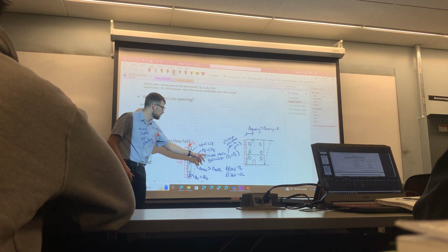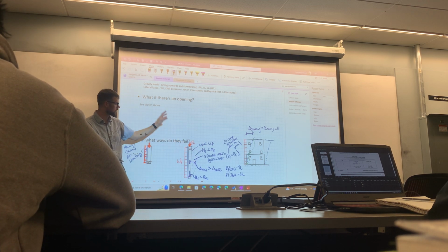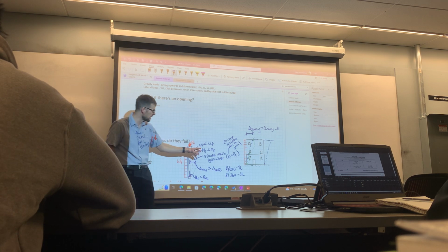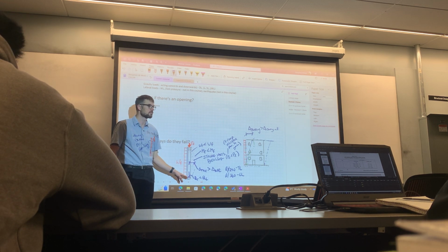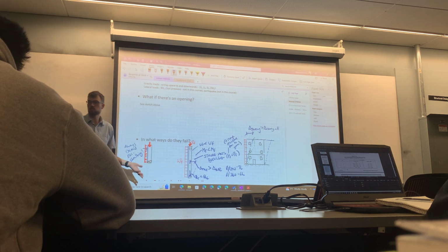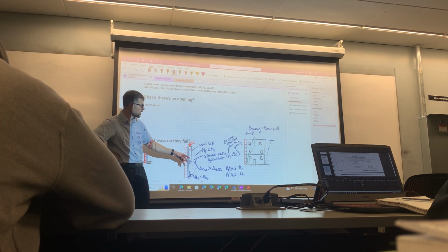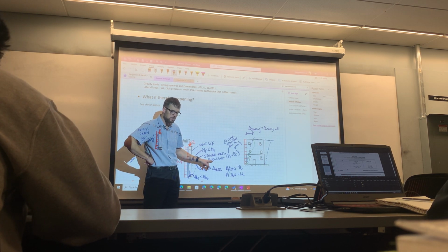All right, we've got module 1, which is the wood products and the constructability and all that. Module 2 is bending, which we covered with the deflection, the bearing, the shear, and the moment. And we got vibration here too. That's not such a concern because these tend to be not so long, but vibration would be a concern for tall walls. Then we also have our module 3, which is strong axis, which is compression member theory.